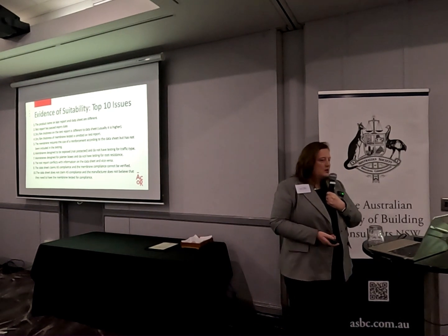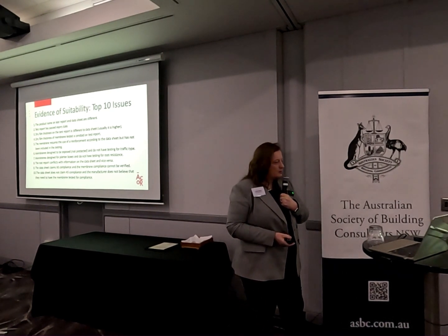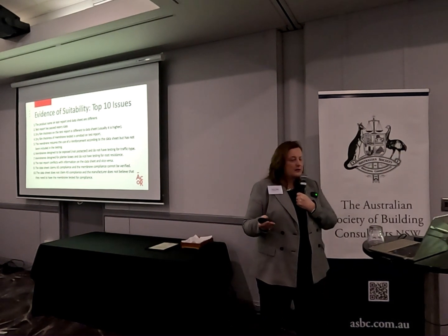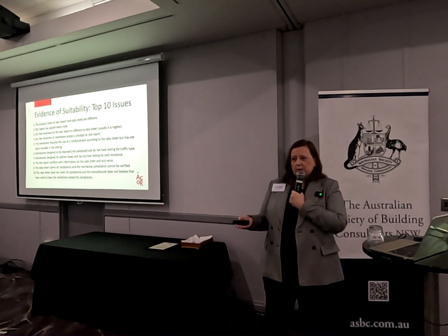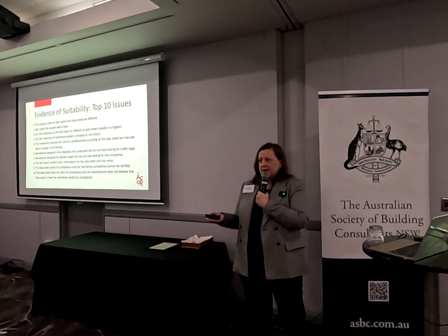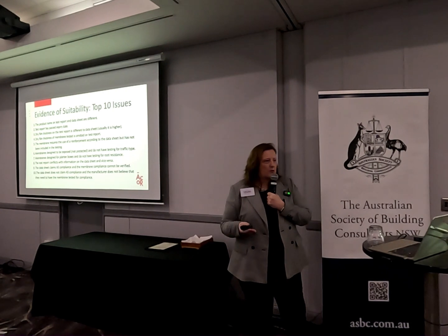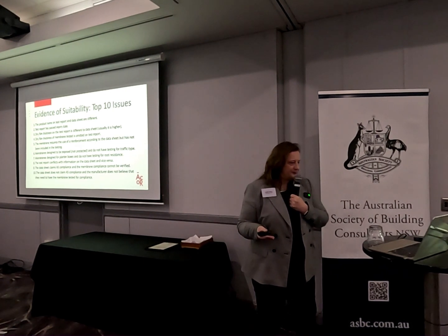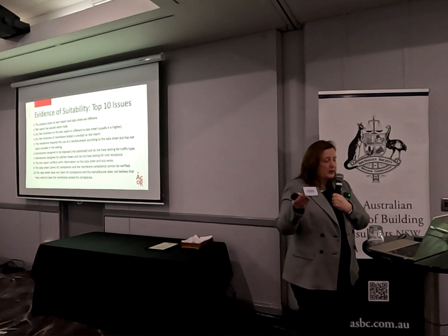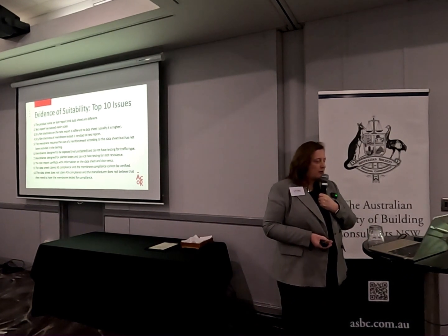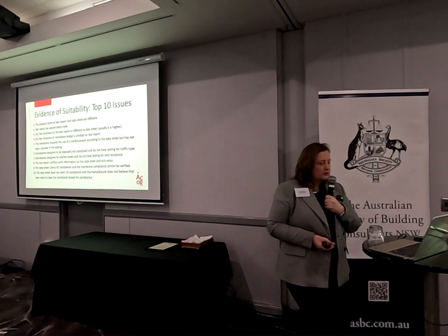Okay, so planter boxes. So that's another one where it's a claim that it's suitable for planter boxes, but it hasn't been tested or have any evidence of root resistance. And that is a key requirement for planter box membranes, or could be landscaping as well, depending on the planting. But that is definitely a requirement that's very clear in AS 4654 Part 2.